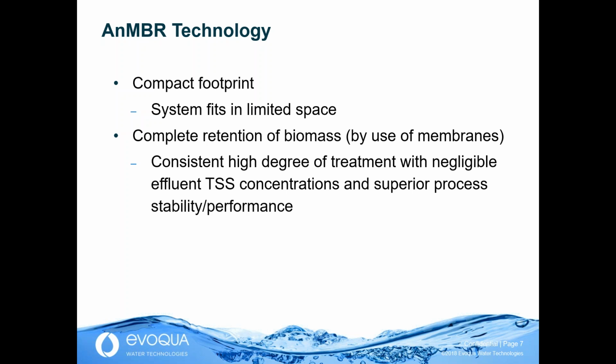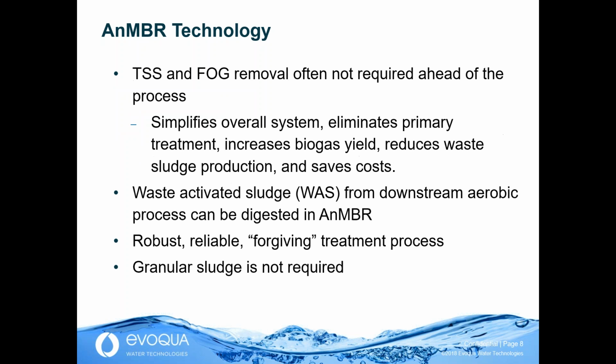This allows the solids retention time and hydraulic retention time to be operated completely independently, because the only way we waste sludge is when we choose to waste sludge, because the membranes will retain that biomass in the system for us. Operating at extended solids retention times will improve digestion, maximize biogas production, and minimize waste sludge production versus some conventional anaerobic technologies.